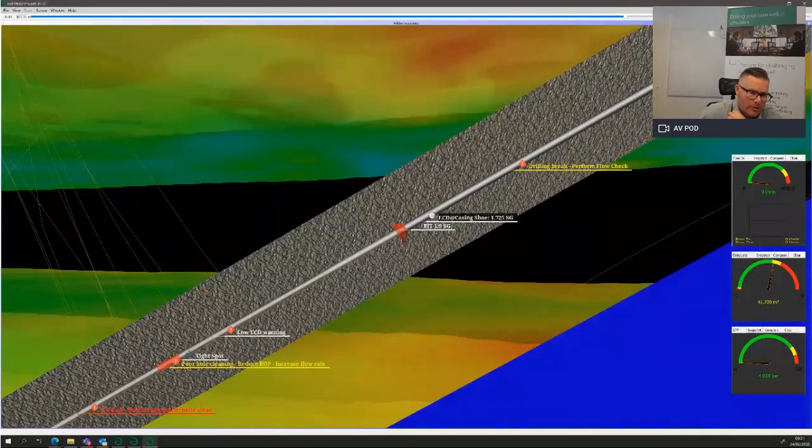And there was also a message here about poor hole cleaning, and also first actions, what to do about that. This is just a playback that I've done. In a newer version, we will also get information about recommended parameters to use on the reduced ROP and the flow rate. We also have a pack-off detection with first action.